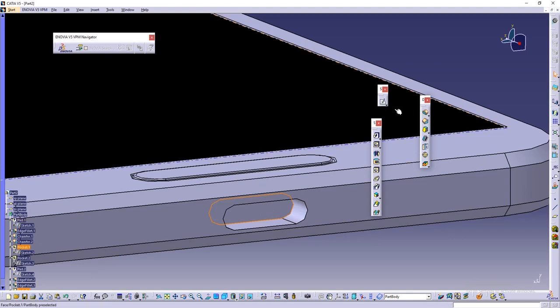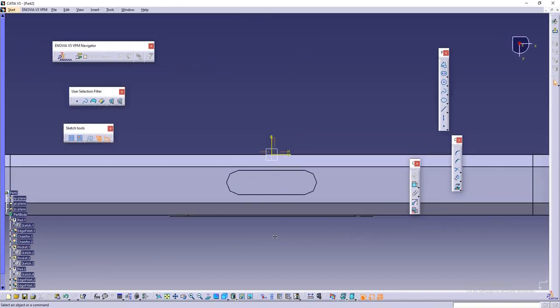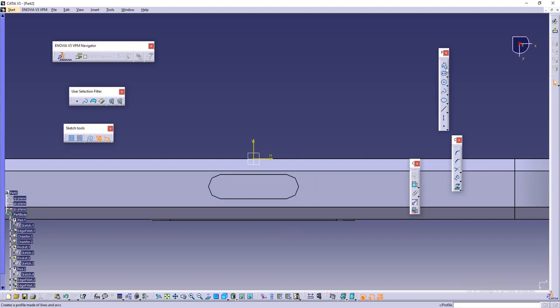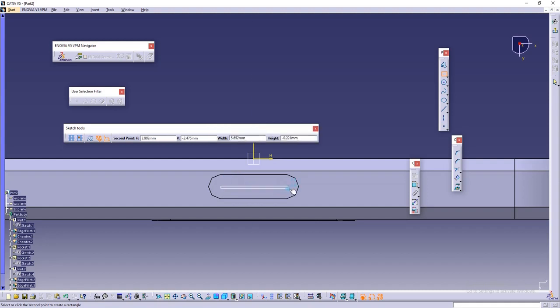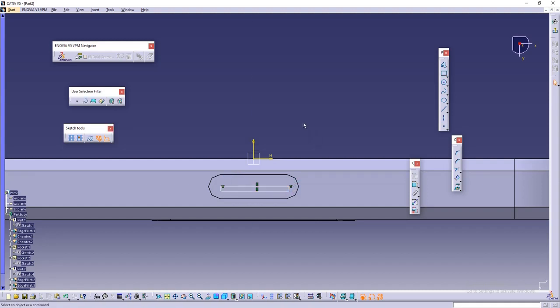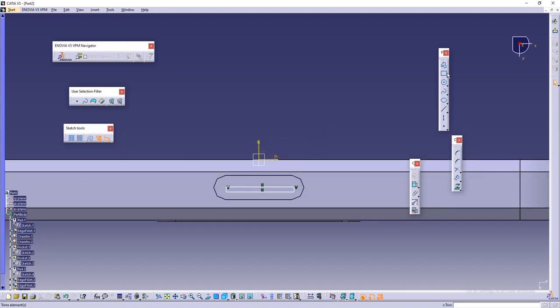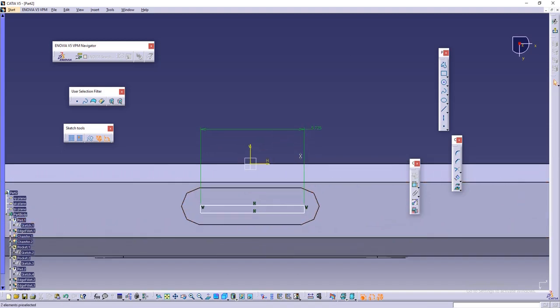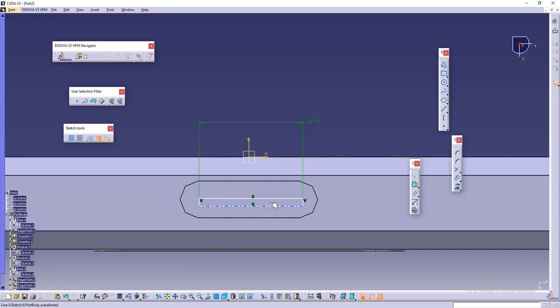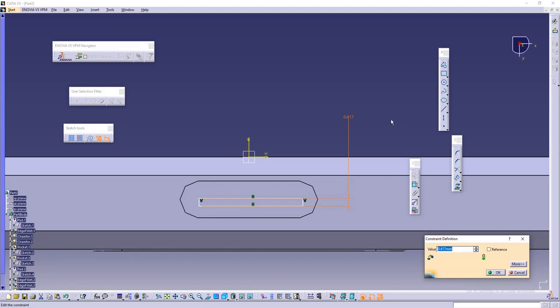Click on the inner surface, go to the sketch option, right? And then there will be a box kind of thing. Let's select any box structure from here till here, right? Then next stage, dimensions. Now it is in the air, so maybe the below dimensions will be different and the top dimensions will be different, right? So maybe you can select like this, like to this, and then you can give some dimensions to both of them. Like 0.4 is written, so 0.7, so I'll just make it 0.4.